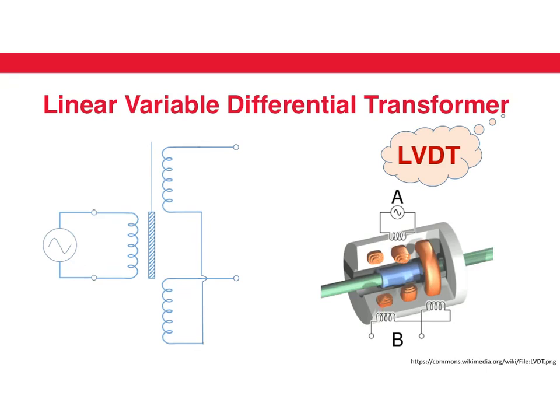The amount of magnetic flux passing through the two coils can be changed by moving this plunger up and down. When the plunger is near the first coil, more of the magnetic field passes through the first coil and a large signal is produced across it. It works similarly in the opposite direction as well. Also, these two coils are connected in such a way that the current through one coil passes in the negative direction through the other.